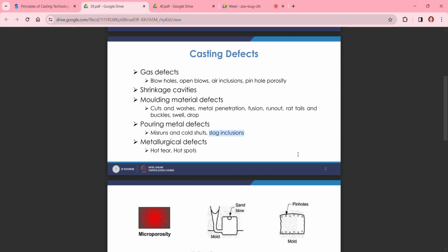So your grain boundaries are going to melt down, and when you apply pressure during a forging process or something like that, your whole casting is going to tear apart from those grain boundaries, because they have already melted. Your whole casting will get broken up, and you will not be able to carry out any heat treatment, forging or hot working processes on your castings.